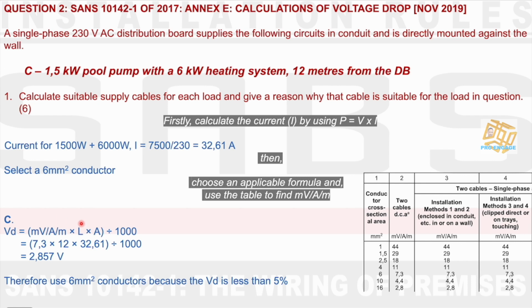So I would then not choose 4 millimeter squared, but rather 6 millimeter squared. And I then go to my table, I line up 6 mil with the correct column, and I have a value of 7.3 for the millivolt amp-meter. I times that by 12 meters, and also by the amps that I've calculated. I divide all of it by 1,000 and find an answer of 2.857 volts. This is a good value. I say therefore use 6 millimeter squared conductors because the voltage drop is less than 5%.